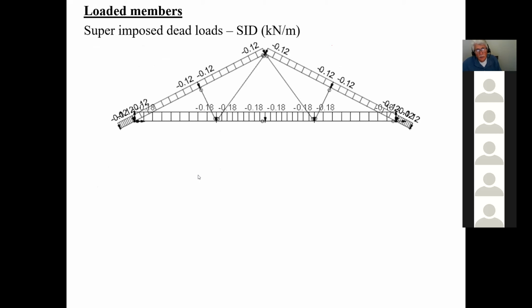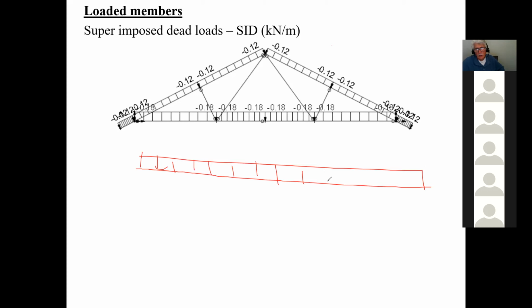So in other words, now what you need to know is with ADA, okay, you got to be careful. Okay, if you don't tell the direction, like here, when the members are horizontal, okay, it's not a problem. You don't have to change nothing. ADA will always put it perpendicular or globally this way. Okay, so ADA automatically does this by default, but that's okay for the bottom chord.